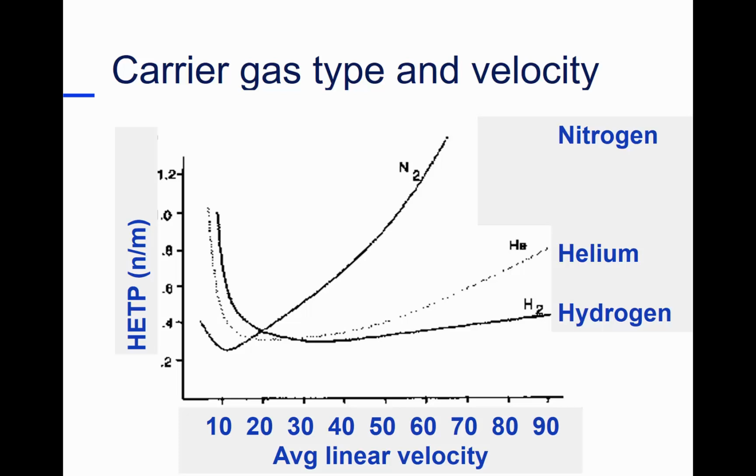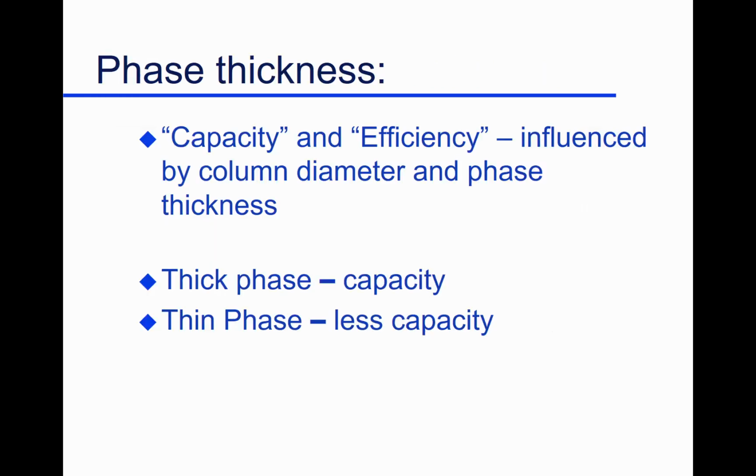So we recommend hydrogen. That is the primary gas by far from a cost and a performance standpoint. Is it going to blow up? As I said, no, it's not going to blow up. You really have to work at that to get anything going wrong with that. So what do we use? We use small columns. We use hydrogen as a carrier gas.